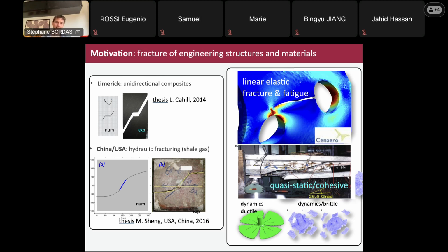And on the bottom case, you have exactly the same type of problem, except that you have now the hydraulic part in the fracture. So that means that you are subjecting the fracture to load coming from water pressure or bentonite pressure, in that case, that you are pumping into the crack in order to make it open, such that you can extract the gas that is going to escape from these shale deposits.